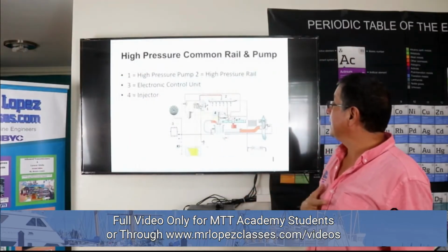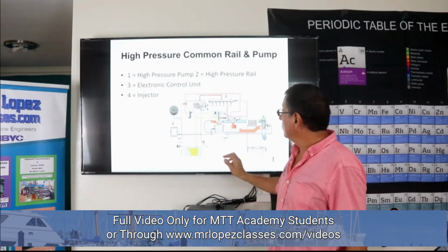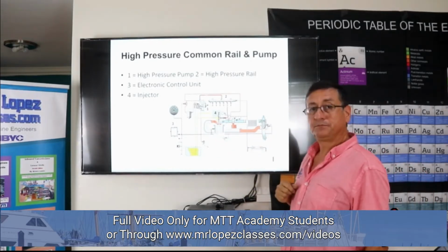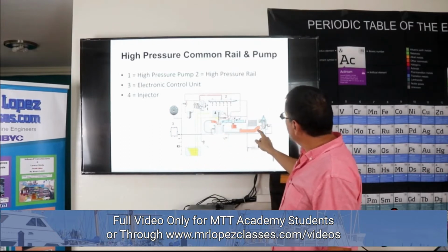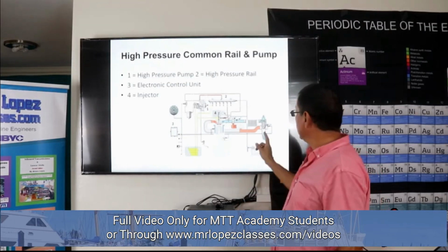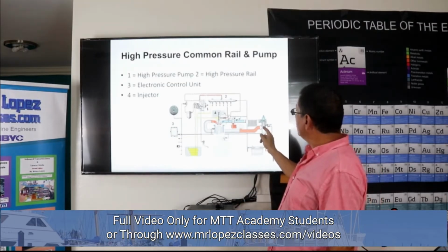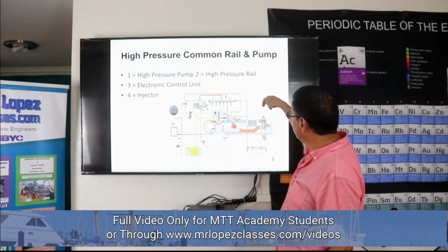I want to read that picture. That picture is of a typical diesel engine with a turbocharger. If you check, this is the exhaust manifold. The exhaust manifold goes into the hot section of the turbocharger and spins it, and the impeller on the other side sucks air from the air filter.